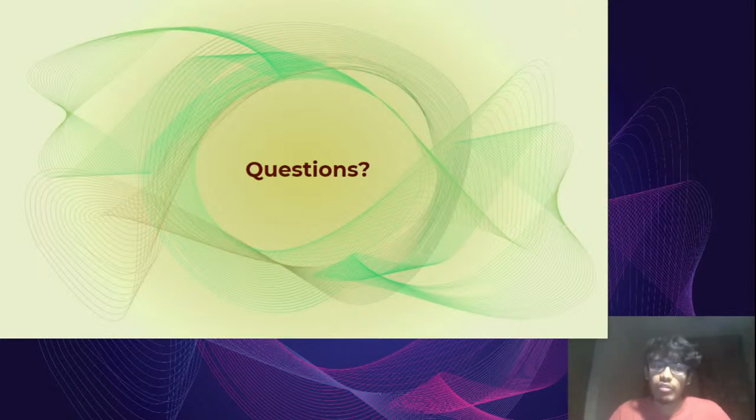So yes, we do have a PCB mill in bits, and we can also use several other, I would say, jugaad methods to make PCBs, like the famous laser printer method, or the toner transfer method, where we print the design using a laser printer and use an iron to imprint it on a PCB and then etch it using chemicals. That's a long method, but that is something I have definitely used at home. So you actually don't need very expensive equipment for simple PCBs.